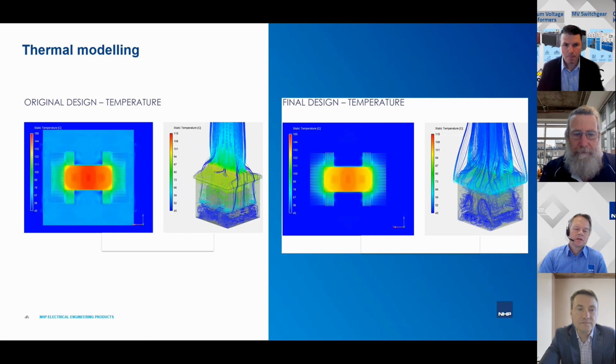Okay, so we can see on the left that the transformer, by the colours, is showing that the main core is where the heat's coming from, and then that core is radiating out through the fins. And what we have with our initial design, as I mentioned before, is air running in the bottom vents, over the transformer, and out the ridge vent. But what we found through this modelling is that we aren't really getting air out of the top as fast as we need to.